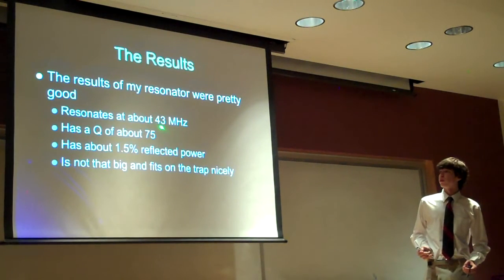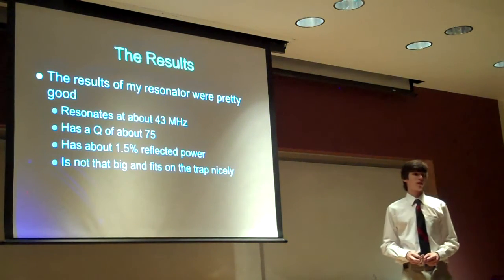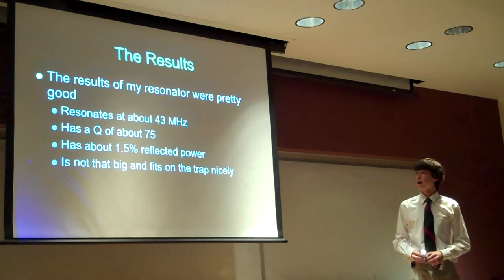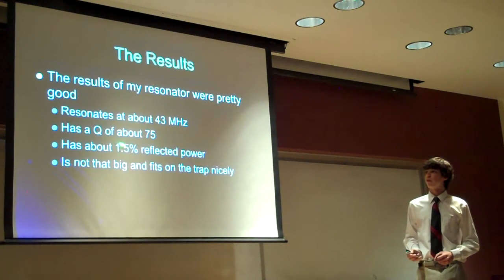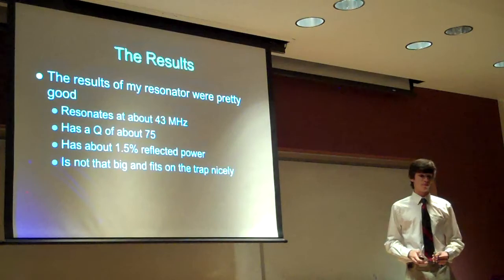Now if I had more time, I could obviously make little adjustments and make it a lot better. Like the Q and the resonant frequency may be a little lower. If you sand the connections, the Q should go a little higher, and we want to see the reflective power go down a little bit more, even though it is pretty low.